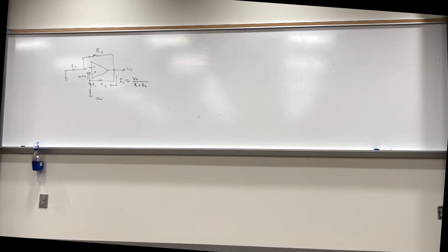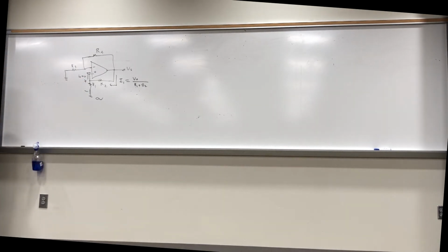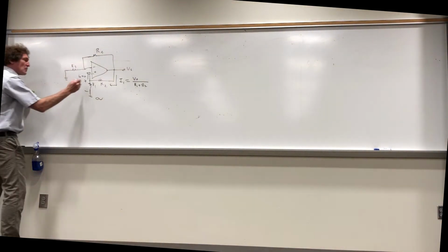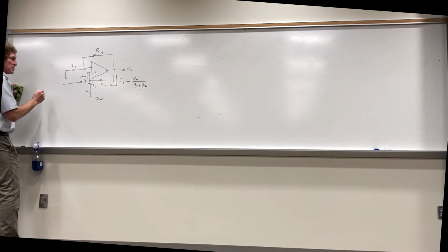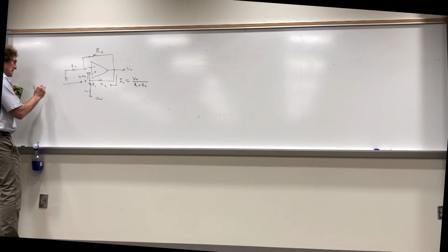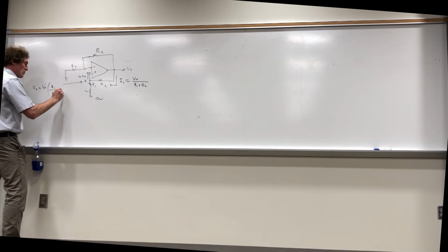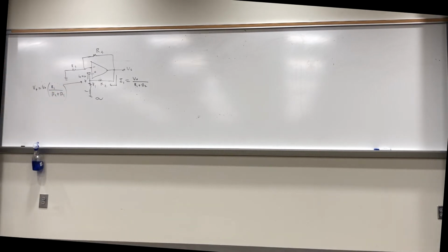All right. Now, with that in mind, we could have done it with voltage division. I want to make sure you see it here. So what is the voltage across this resistor? I1 times R1, right? Or it's simple voltage division between the output and this plus terminal. Do you all see that? And I can say that this voltage right here at the plus terminal, V plus, would be V out times the quantity R1 over R2 plus R1, correct? Y'all with me on this?